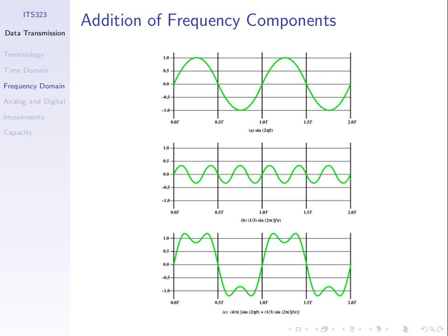You need to do some analysis to find the frequency components, given this signal, and to then work out the spectrum and the absolute bandwidth. Well, what about this plot? Same signal, but in a different domain, from a different perspective. If I give you this, you can immediately see the spectrum and absolute bandwidth of the signal. The spectrum, there are just two components at 100 and 300 hertz. The bandwidth is the difference between the two, 200 hertz.